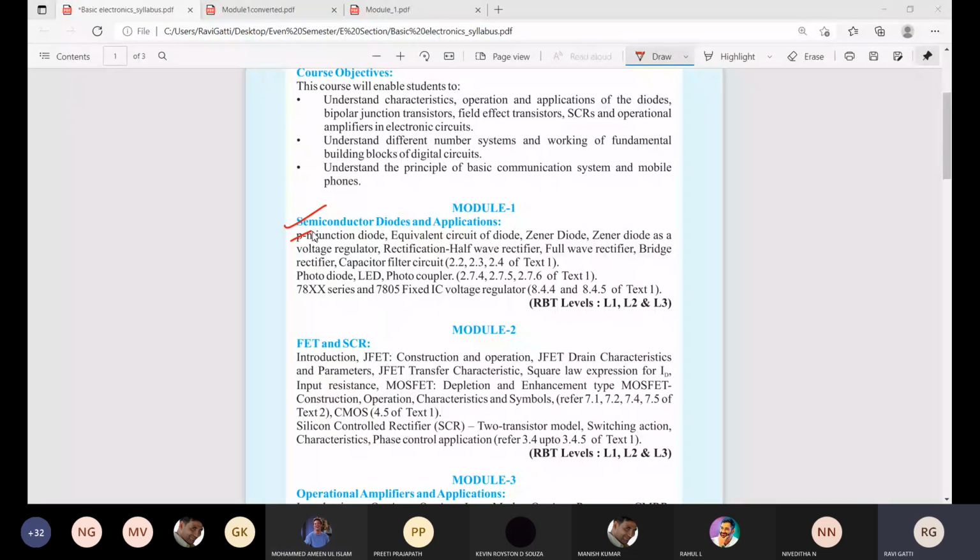Yes, very good. So basically, we want to convert the given AC current to DC current. Why? Because most of the applications we run in our home appliances work on DC current. Okay, so it is necessary for us to convert the AC signal to DC signal. So therefore, we use a circuit called a rectifier. Okay, so how are we going to use this? What you mean by half wave rectifier and what you mean by full wave rectifier, we will be seeing.